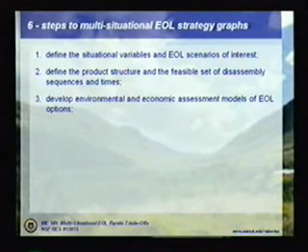Number 3, develop an environmental and economic assessment model. Right? You need a life cycle assessment model for the end-of-life scenarios. What's the impact of transportation? What's the impact of landfill? We need an economic model for transportation. Disassembly, the disassembly times. If I've got all these different options, how do I model how long it's going to take to disassemble the coffee maker? Because it's going to be related to how much I have to pay somebody to do it, and that's going to be related to my cost. So we need these models. So step 3 is establishing these models, and we've done a lot of this modeling in the class already.